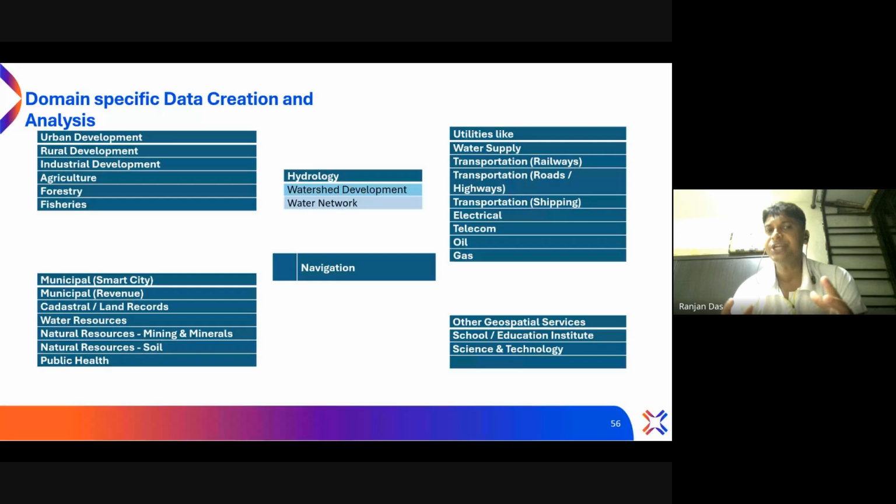You are saying your watershed is there, and how that will be developed. It's something on a regional basis. Watershed development is a program from the government, PPP, participatory planning. For watersheds, there are a lot of GIS utilities. If you have your DEM and your images, you can directly use that DEM to generate the boundaries. I have watershed boundary, sub watershed, micro watershed, mini watershed, even basins and sub basins. All these things can be prepared by this GIS technology.